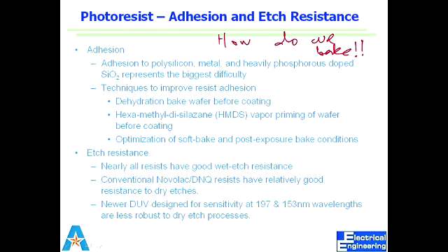Especially if you use dual-side wafers, where you want to use both sides, I don't want to put my wafer on the hot plate at all because my lower side is going to get dirty. Of course, I can do a piranha clean to clean it, but it's quick. And putting it in an oven is quick too. But what is the downside with the oven?